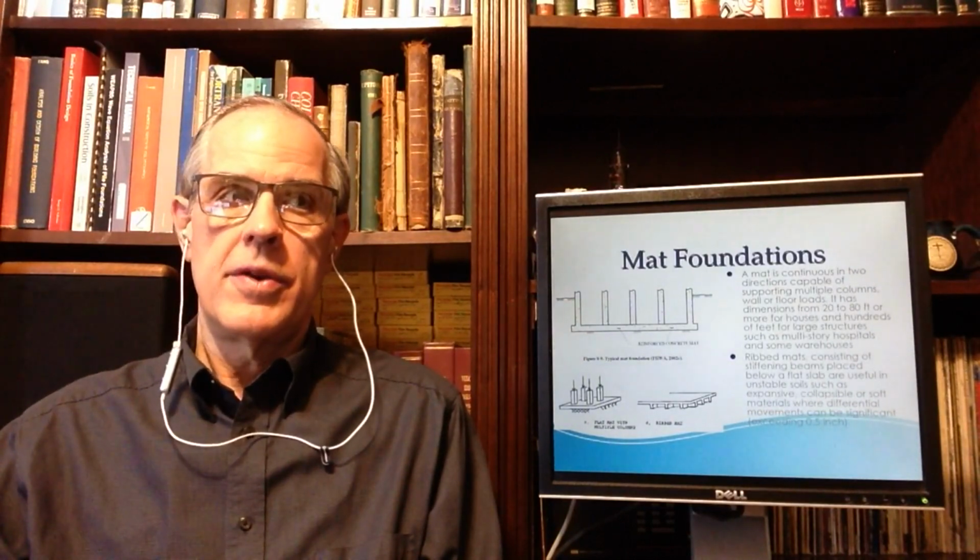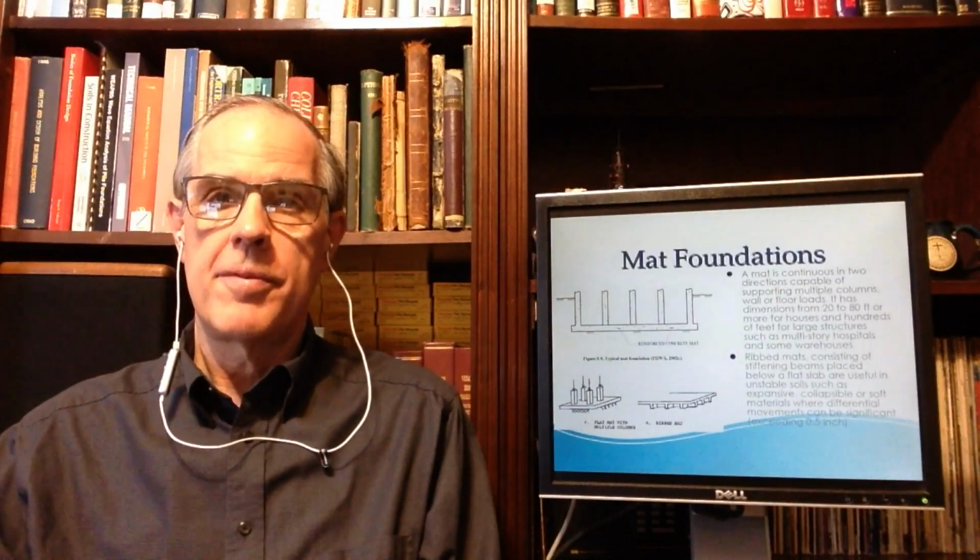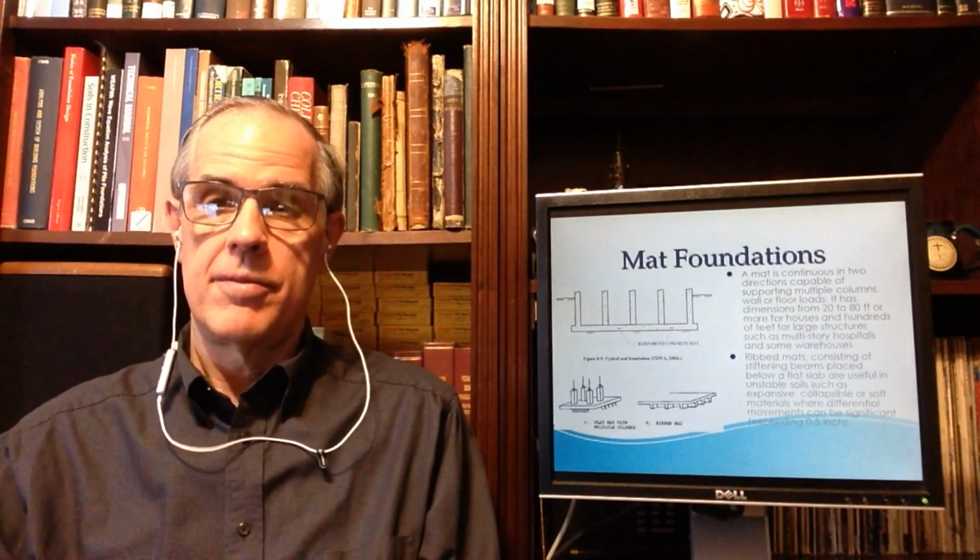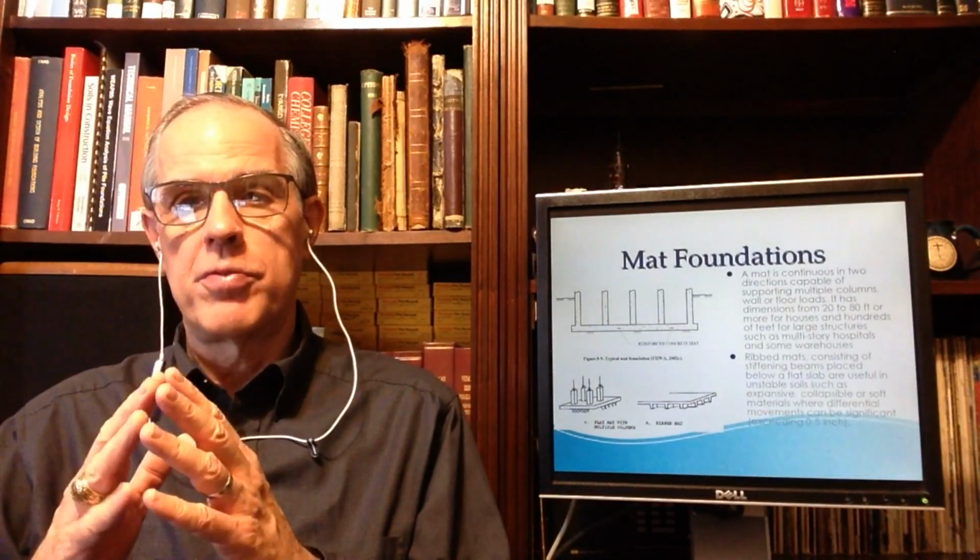Mat foundations are, as I said, very large foundations. Most of the time, they interact with the soil. And when I say interact with the soil, and we'll talk about it in just a minute, they are flexible. They have some flexibility. You remember when we talked about elastic solutions, we had purely flexible foundations where the soil conformed itself to the foundation, or you had rigid foundations where the foundation was perfectly flat usually, and it didn't vary, and the soil just had to adjust to that. Well, no foundation is purely one or the other. They are a continuum. Mat foundations tend to be, we normally assume for spread footings that they're rigid.